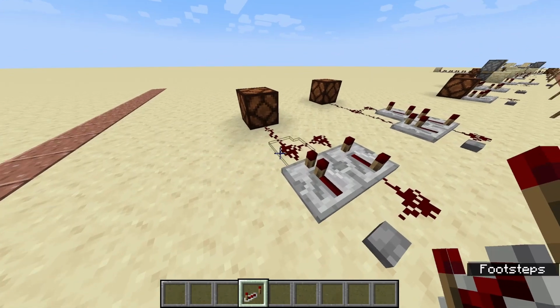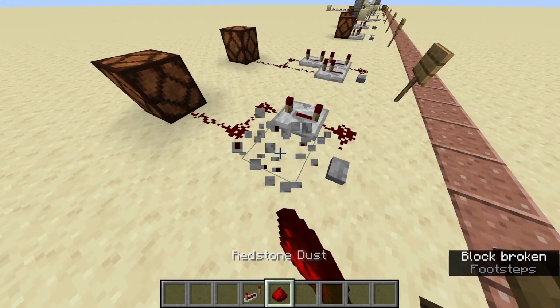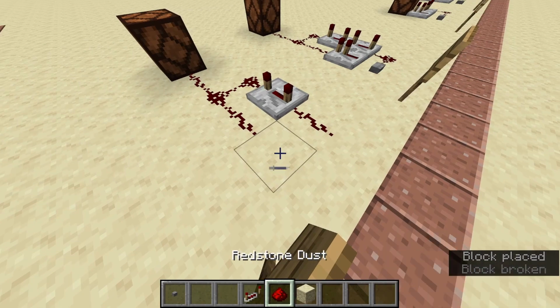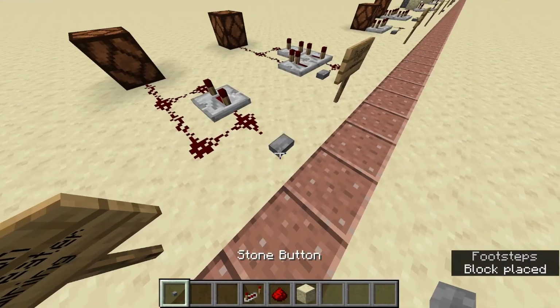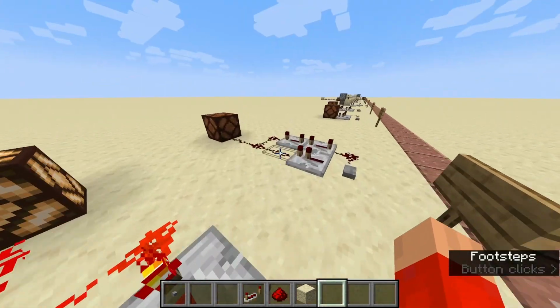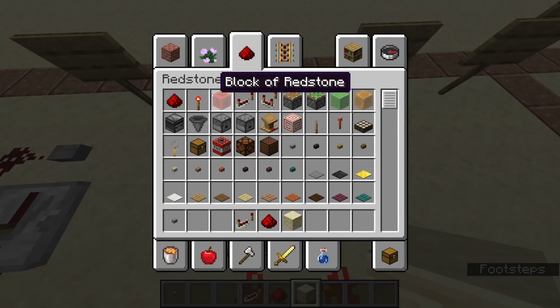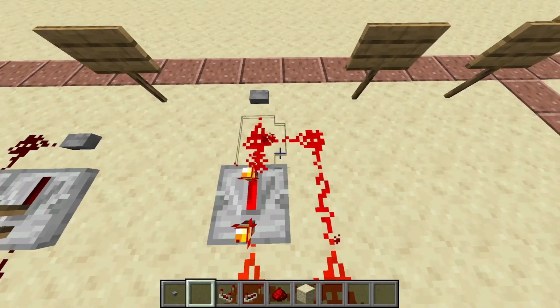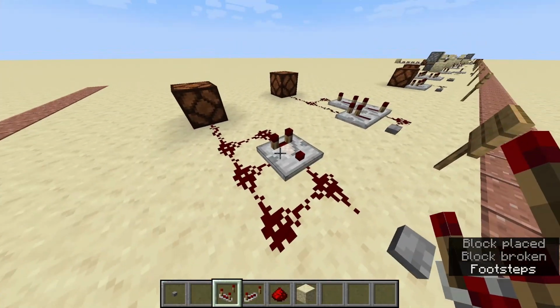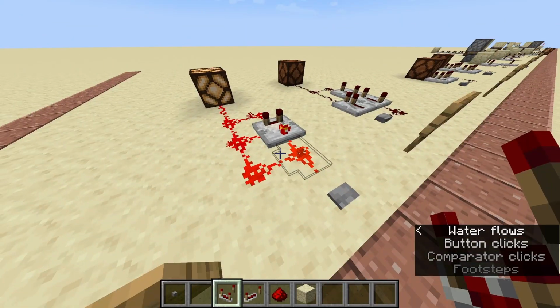Now just a second to tell you, one thing you can't really do is power a pulse extender like this, or you have a circuit that will never ever turn off. So this will always stay on. Although if you do use a comparator, you can make another design for this, which does actually turn off eventually. But yeah, this depends on how you do everything.